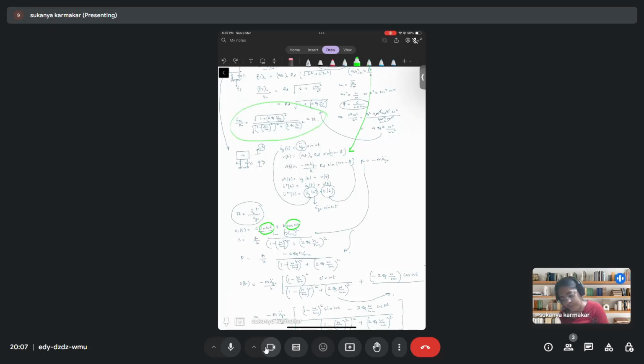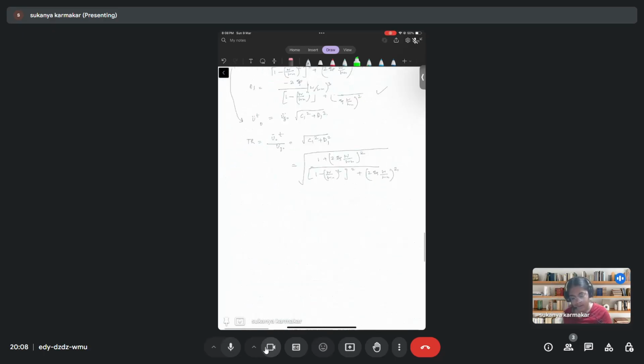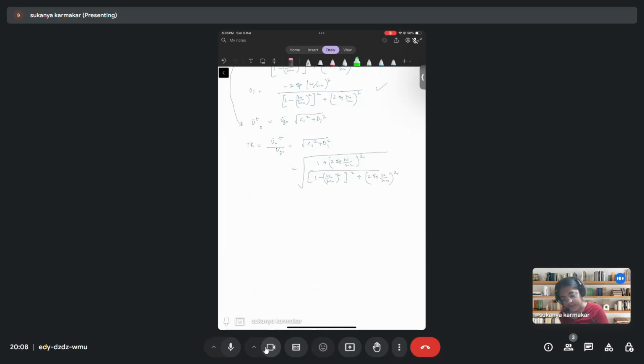So the expression for force transmissibility is same as that of transmissibility when the base is moving. So, in transmissibility, if we provide a ground acceleration, what acceleration will it transfer to the spring mass system?